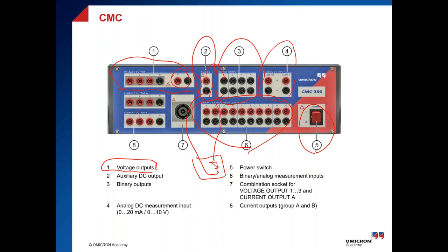Current and voltage can be measured and recorded by using a special, dedicated software in the test universe. We call it the analyzer, and this analyzer can help you do many functions like direct measurement, transient recording as a portable fault recorder in some cases where you don't have a fault recorder. It can be used also for trend recording and for harmonic analysis. All of those functions can be used by the analyzer, but keep in mind that if you need to use the 4 functions, or at least the most focused current and voltage measurement, you need to order